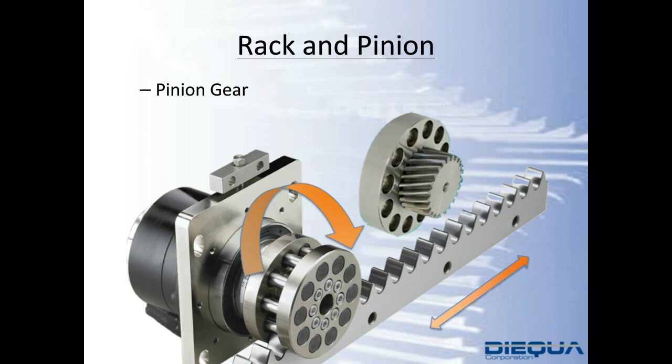A helical cut gear, while higher in torque capacity than a straight cut gear, induces an axial element as a separation force. So not only do you have separation force radially out from the rack, you also have a thrust force of the gear in or out of the gearbox face, depending on the direction. Having the ability to directly mount this pinion gear onto the face of the reducer has some advantages that we'll further develop.